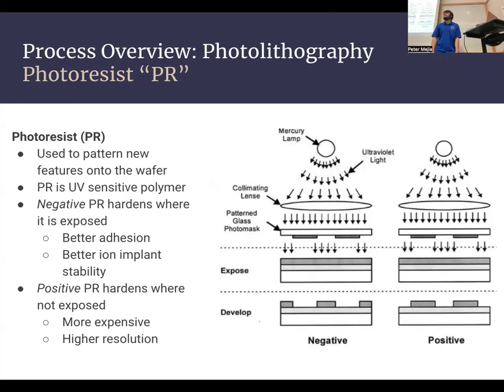Are these photo masks actual size of what's gonna be put onto the chip? Is it 1-to-1 or are there some lenses going on? I'm pretty sure that since we're using a contact lithography machine, it's gonna be 1-to-1. The entire wafer gets exposed all at once.